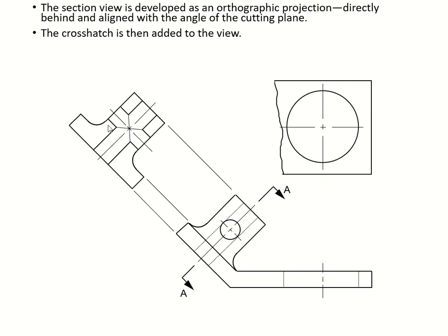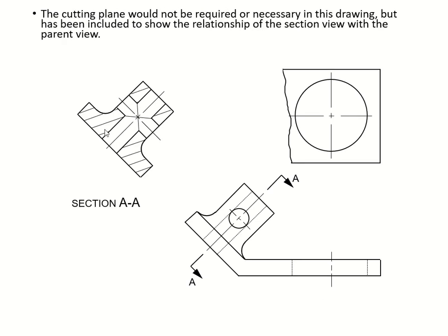And of course you have to show visible lines because you already cut it, so the surface has been exposed, and we put our crosshatch in the exposed area. The rest of it is just hollow, because you're dealing with a hollow cylinder right there, and then here is your circle. So that's your section AA, which is your auxiliary or partial sectioning.